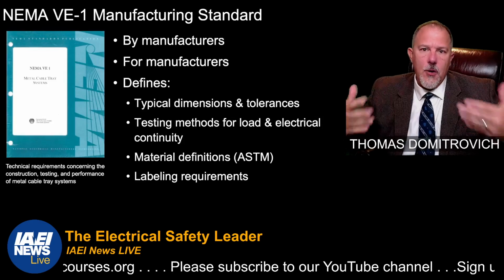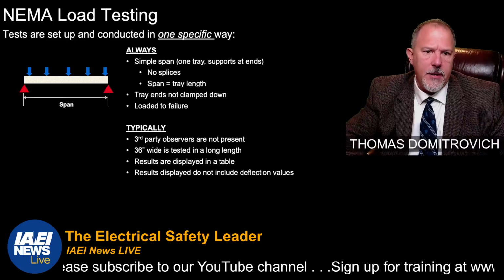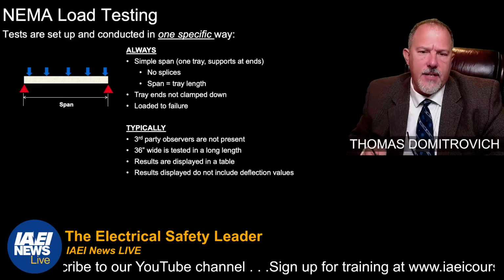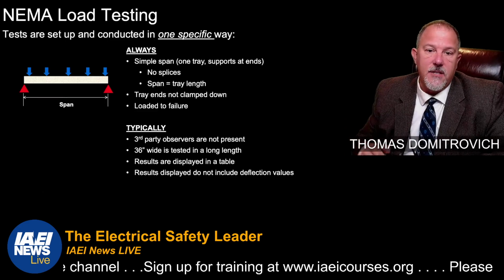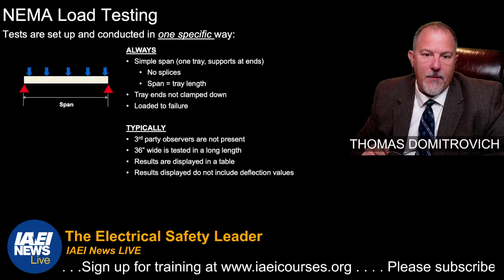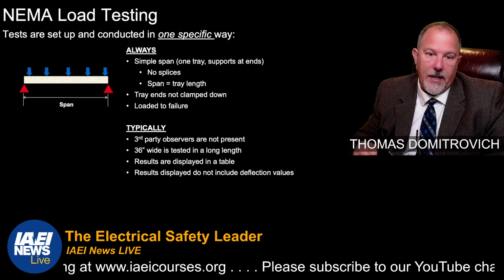How to test for loading, etc., and labeling all your materials. Tests are conducted in a specific way. Simple span, no splices, span tray lengths, tray ends not clamped down, and then a loading to failure, and that gives us the weight capability.